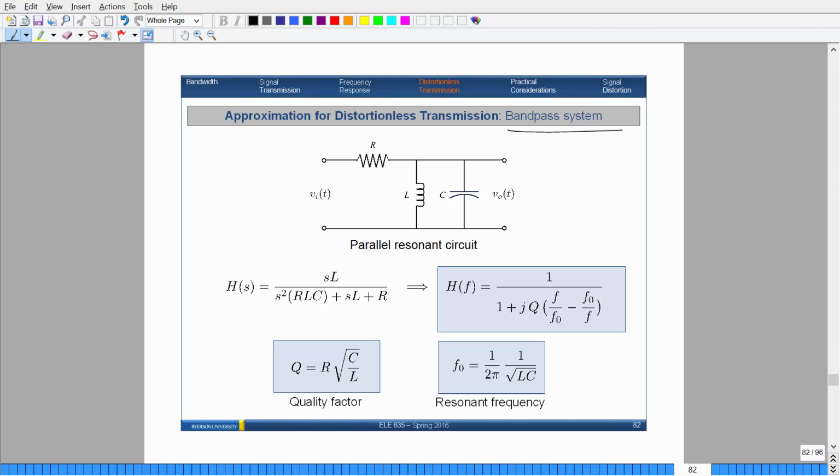Can you repeat what you said about baseband? You don't remember what baseband was? Yeah, but can you just repeat the region? Okay, baseband means that the frequencies range from 0 up to some point. It's centered at 0. Bandpass is away from the origin. So baseband looks something like that, and bandpass looks something like that, and this is FL and then FU. Does that make sense?